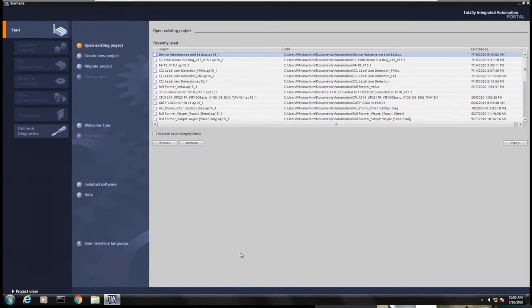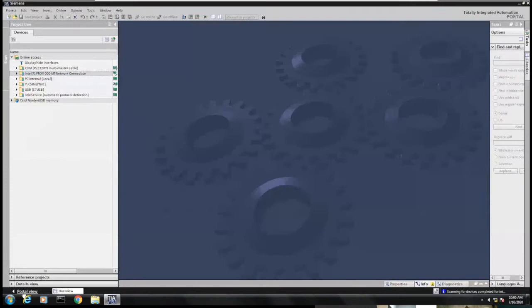So first and foremost, we're going to start with our PLCs. One of the main points on the flyer that we sent out to everybody was uploading from S7-1200s and S7-1500s. So we're dealing with an Ethernet connection. To the left of me, you can't see it here, but I have an S7-1200, I have an S7-1500, and I have a KTP-400 basic comfort panel.